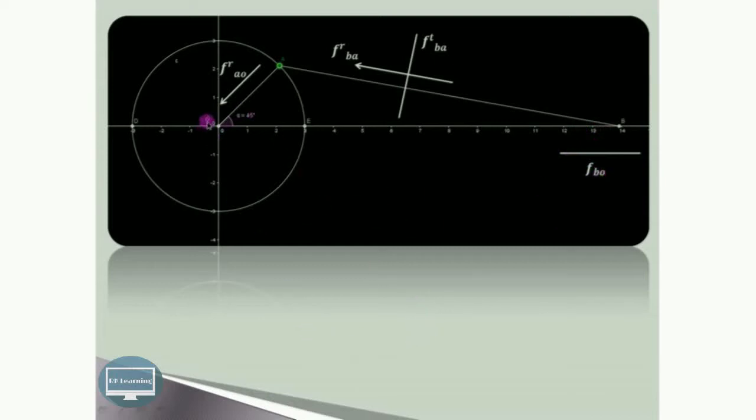Now let us consider this fixed point O in space over here. So this is the point O. From O, we'll consider our first vector. This is nothing but the radial or centripetal acceleration. Now this radial or centripetal acceleration is directed towards the center, so we have to follow this particular direction. Here the center is nothing but O, A with respect to O. So this is the direction. We'll draw a vector parallel to this vector from O with some suitable scale to a certain centimeter length.